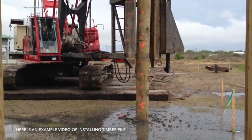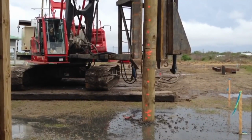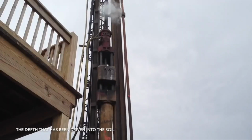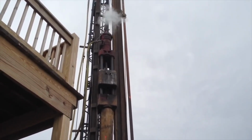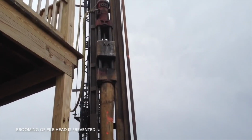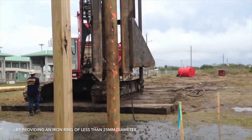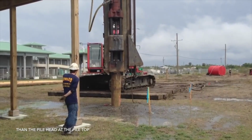Here is an example video of installing a timber pile by using a Vulcan hammer. The marking on the timber pile indicates the depth that has been driven into the soil. Brooming of the pile head is prevented by providing an iron ring of less than 25 mm in diameter than the pile head at the pile top.